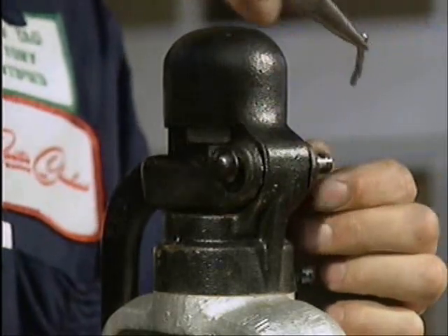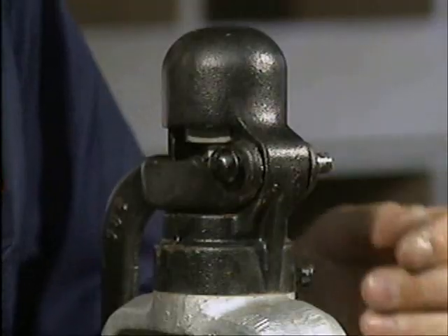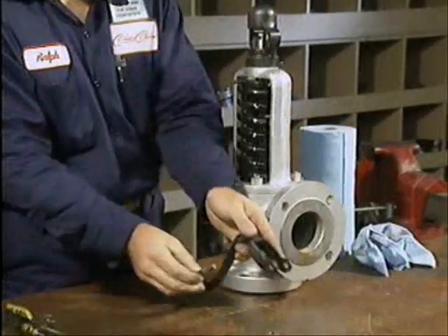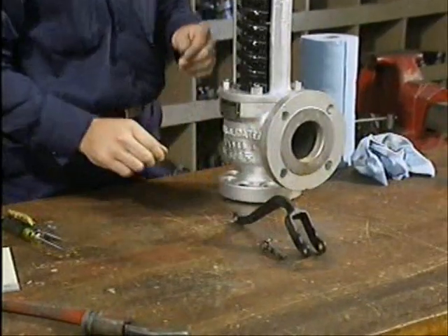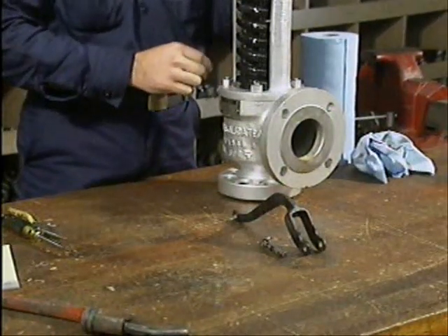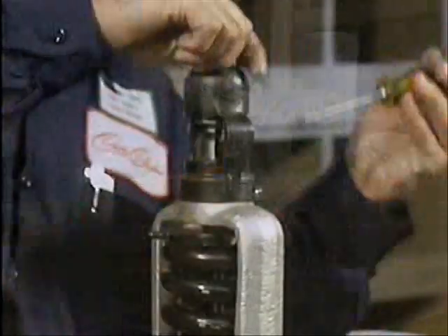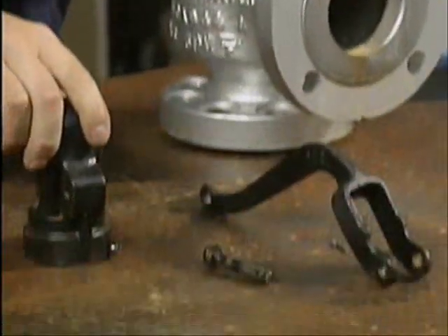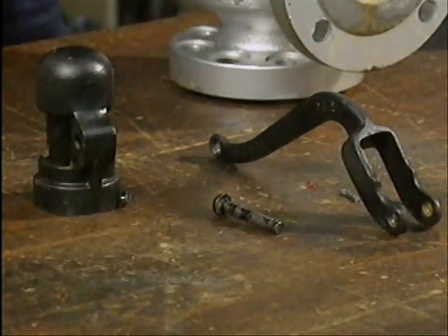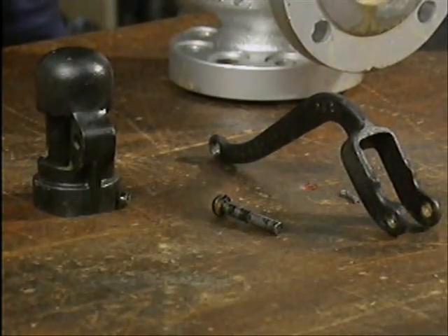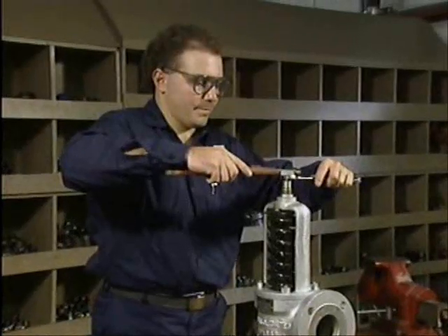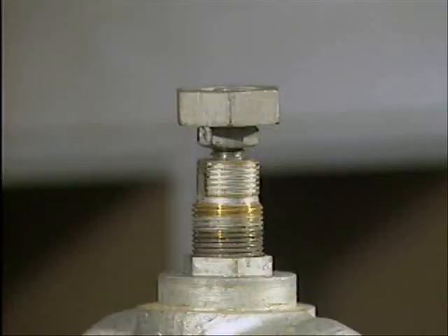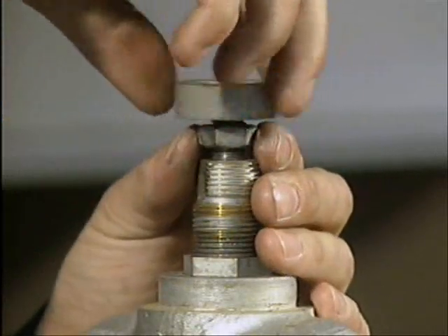First, take out the cotter pin that locks the pivot pin in place. Then pull the pivot pin out. As each part is removed, set it aside in a safe place so it won't get damaged. Next, take off the release lever and then the cap that protects the top of the stem from getting dirty or being bent. Then, break the lifting nut and the lock nut free. Turn them off the stem and set them aside.